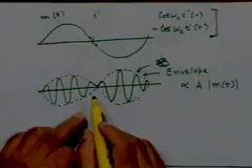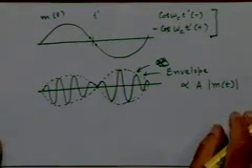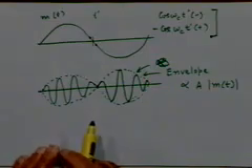So when you look at a DSBSC waveform, let's say on an oscilloscope, I believe you will go through a communication lab sometime. You must look at this feature carefully, that indeed at the points of zero crossing the carrier goes through a 180 degree phase shift. The carrier looks as if it has gone through a 180 degree phase shift at the zero crossings of the message waveform. So that's a typical picture of the DSBSC waveform in the time domain.